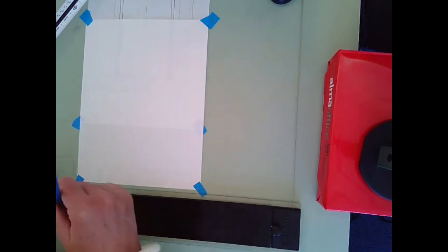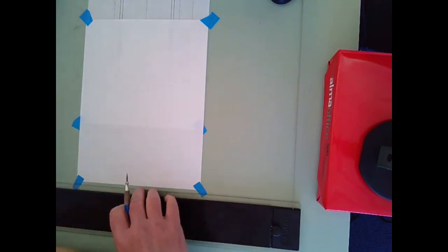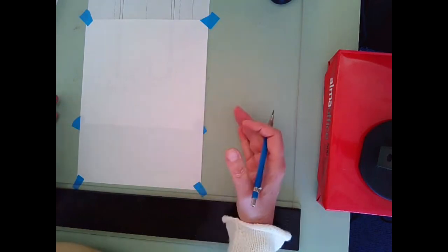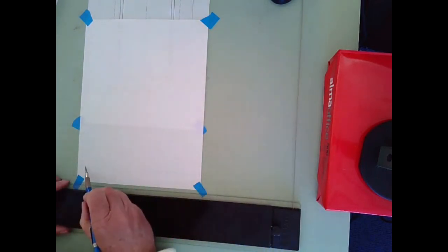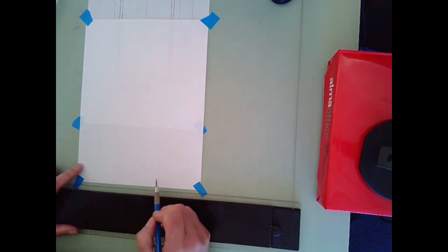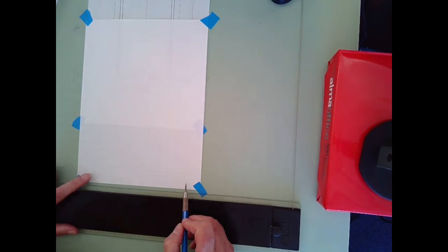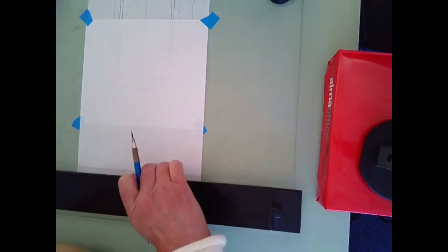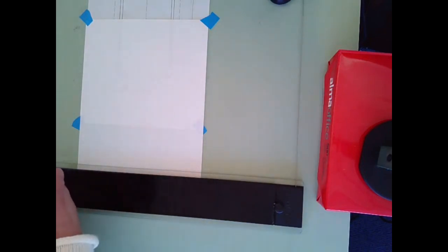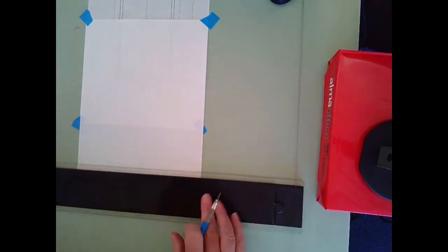If you have any questions, the sample is taped to my office door. I'm not going to grade anything going forward if your title block is not correct. So you're 1 inch from the top, you're a 1/2 inch gap, and then you have to use guidelines. Your name is centered at 1/4 inch high. The date is over here, and the assignment number is over here at 1/8 inch high. So that's going to be a requirement for submitting, because by now you should have gotten this down.